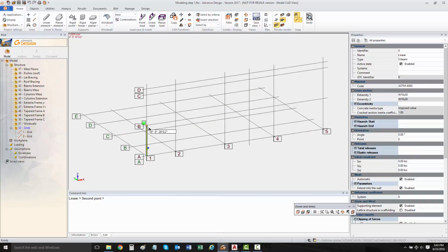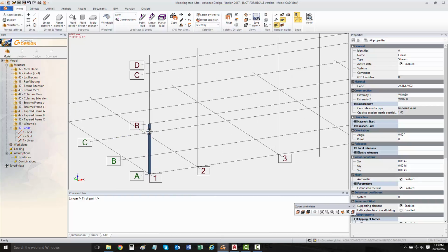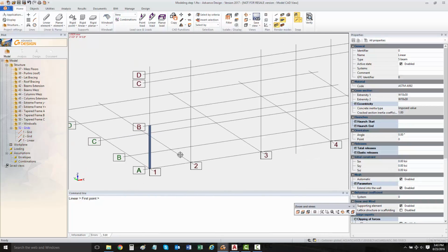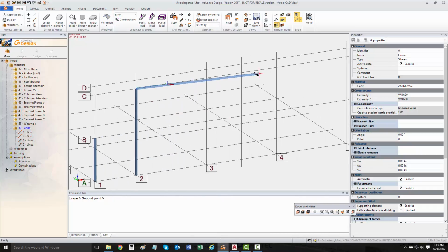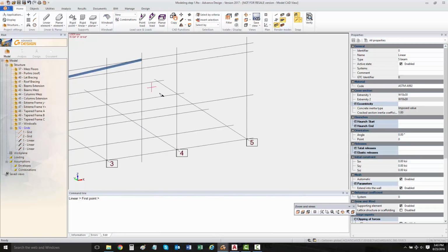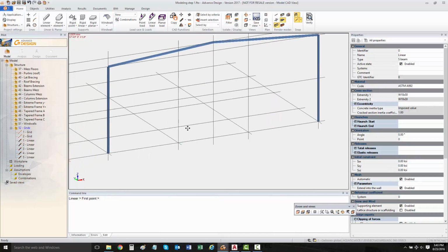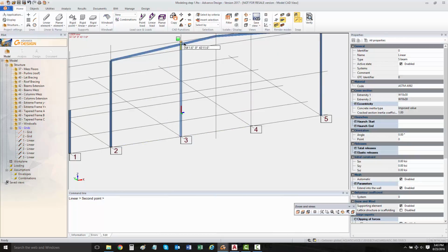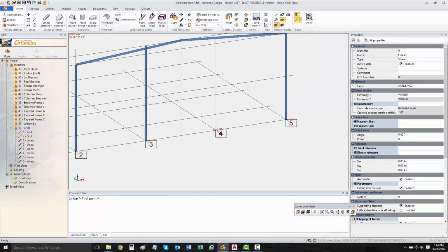And we have a lot of snap points that we could connect to. We're putting in some W sections for our heights, and I'm going to just draw out this simple geometry that we have, and we'll be able to do any other modifications we want to them afterwards. I'm going to add in these members here, and they're slightly just a bit longer.